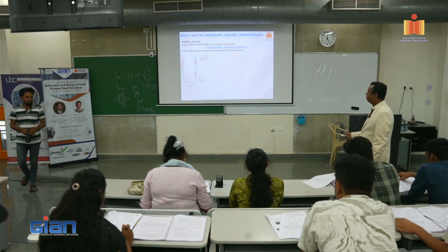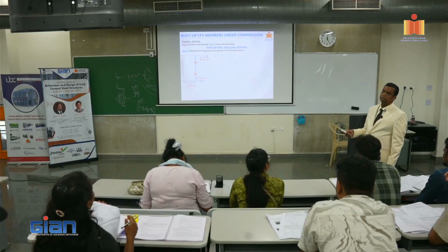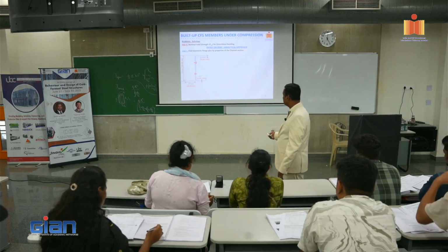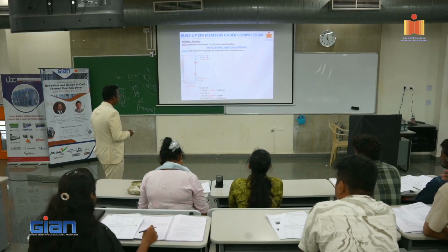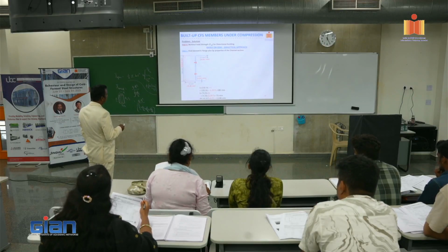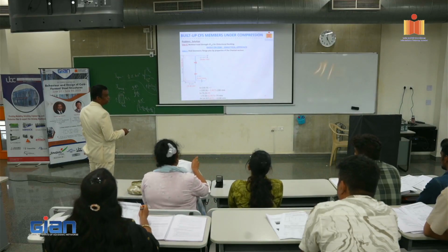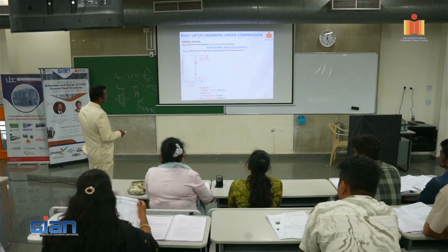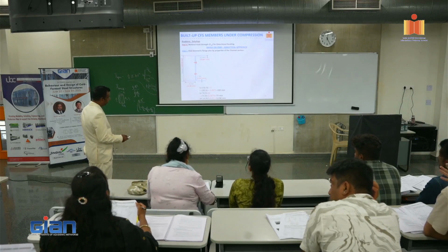So now we have to find out the geometric flange plus lip properties of the channel section. Why? Because there are equations in the code provisions for which you have to calculate using only the centerline method. The centerline method, the H is 199.96 minus T. So what is T? T is 1.957. So this is 199.96 minus T by 2 at the top, minus T by 2 at the bottom becomes T. So when you do so, you get 198. This B is 74.96 minus T, and then this D is equal to 14.957 minus T by 2. You get these values. Now why do I calculate these values?